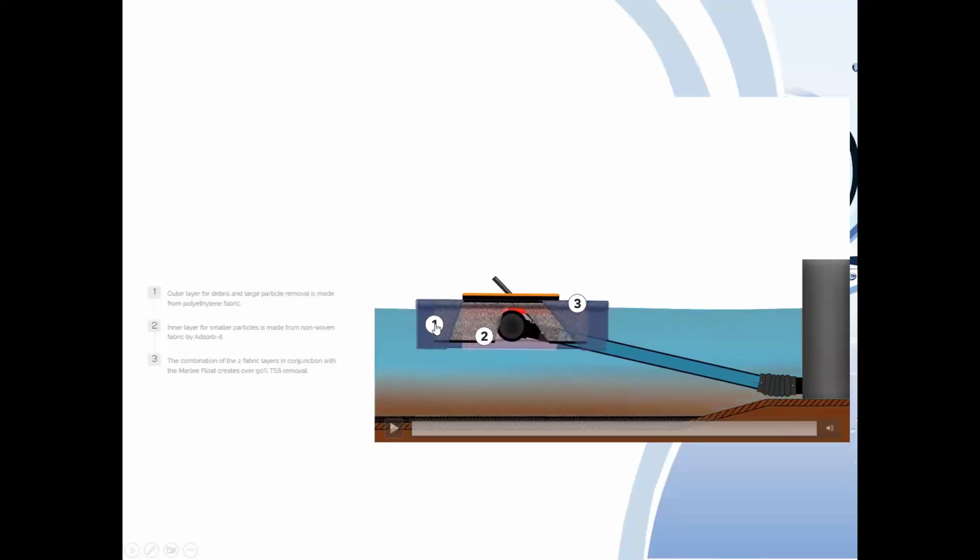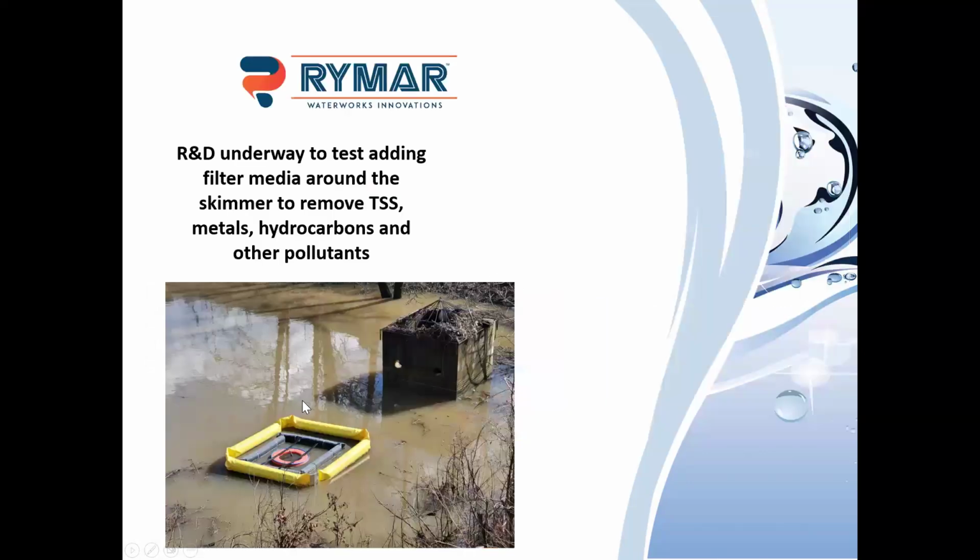And then the idea is the skimmer is pulling the flow through those filters to get to the skimmer to get discharge. The filter is open on the bottom. It hangs about 3 feet deep. So the idea is that if water is below that 3 foot depth, there's not enough turbulent force to bring it up and get discharged by the skimmer. So we're filtering the top 3 feet, allowing gravity to do the job below 3 feet.